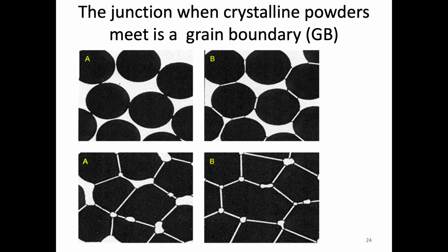So what we're going to try to do with the sintering process is join these particles together to form a homogeneous part that is one piece, not a collection of individual particles. And how that is done is in the contact regions. Where these particles are touching, what we tend to see is a formation of a grain boundary, right? So now these are bonded together. There's a bonding happening when you have a grain boundary. And so the more and more grain boundaries we have, the stronger and stronger this is going to become.